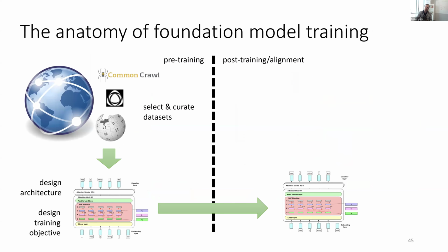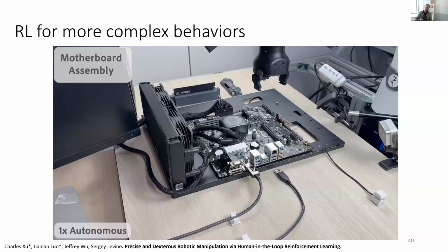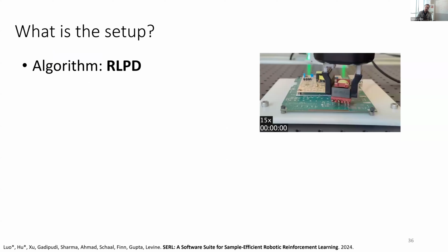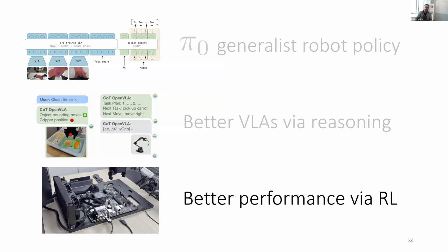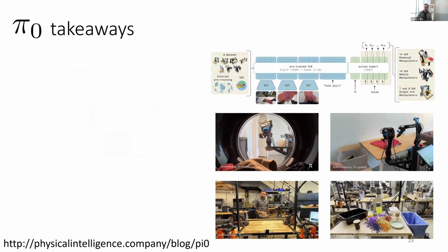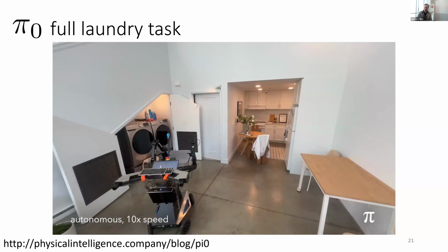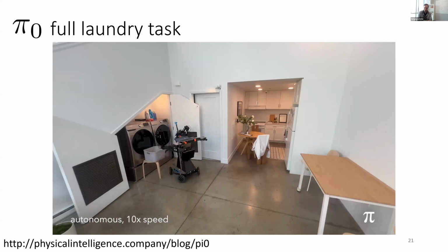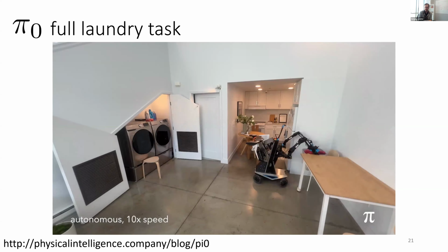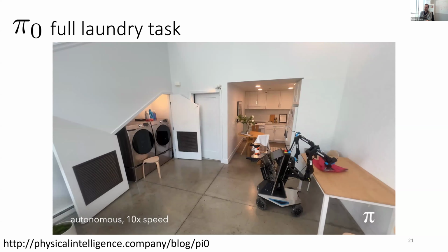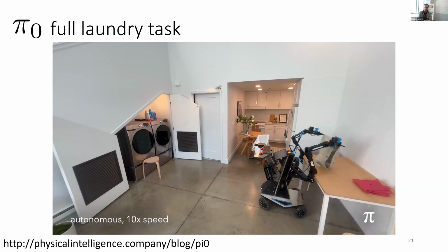So we did do a little bit of mobile manipulation work even in the initial release. Let me pull up the video. But we just had much less of it. That was purely for a logistical reason, which is mobile manipulators are hard to set up, and they take quite a bit more care to operate, because you want to make sure the robot doesn't decide to drive out the door and down the street. But this is the mobile manipulator. The mobility here is also entirely controlled end to end. There's actually no difference to the policy. As far as it's concerned, controlling the joints is exactly the same as controlling the wheels. And when it stays still like that, it's because it's choosing to stay still. So there was nothing special for that, but the environments are much more static.